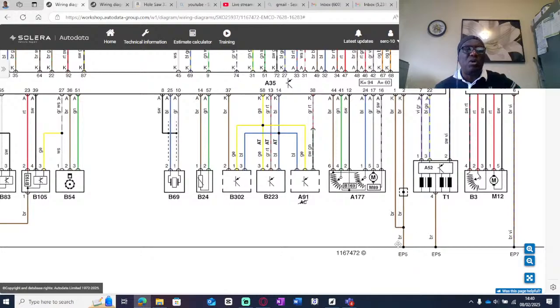If something goes wrong with this 8-point, corrosion and other things like that, you are in trouble. All the electronics will not work right. So it is important to check your ground side, to see that it's still okay, because once corrosion goes in there, sometimes it will give us issues.